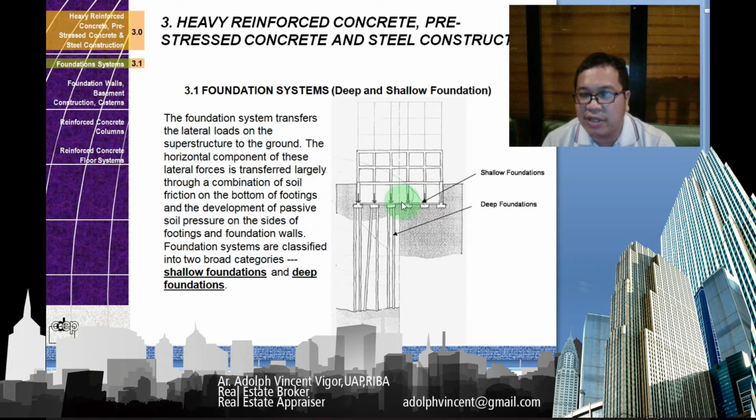In shallow foundation, you don't need to put piles anymore. It's just resting above the ground. So it would really depend, class, on the recommendations of your structural engineer after a geotechnical analysis has been conducted. So it's really important that you understand these concepts.